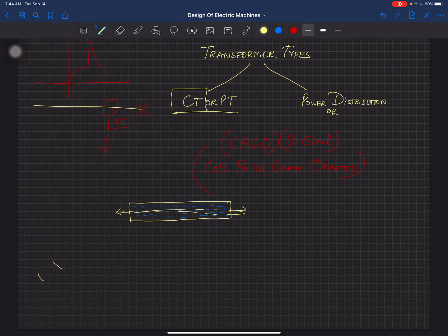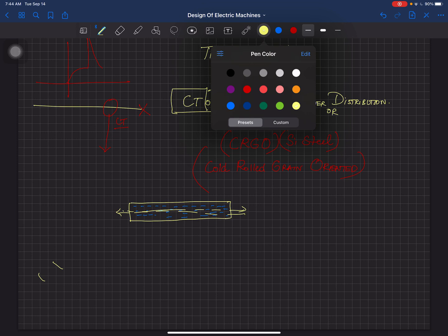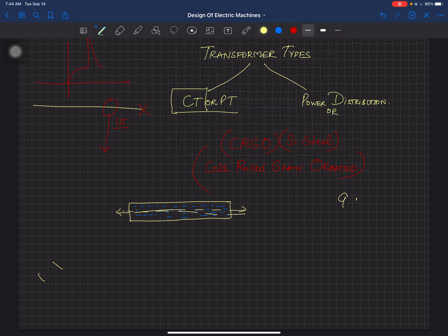And one thing which I missed in the very start also, is that the transformer is the only device in electrical engineering which can achieve 99.9% efficiency very easily, if it is designed very carefully, and if it is working at some point of load. Not certainly at 10% or 20% of load, because the max efficiency curve is not there, but it can work at 99%. There is no other device nowadays. Some power electronic converters are reaching an efficiency of like 98 to 99%, but still the power transformer is the only device in electrical engineering which has the ability of having a higher efficiency.